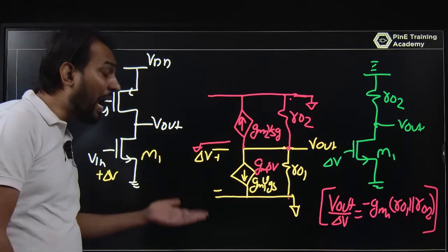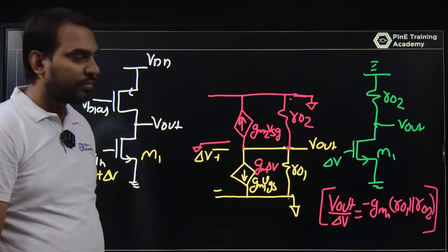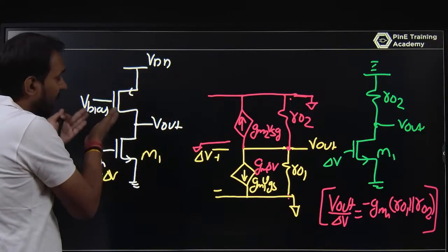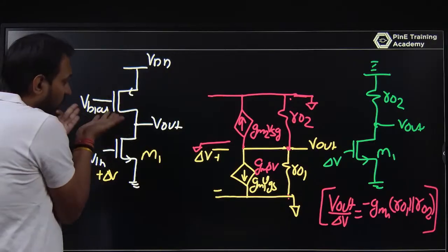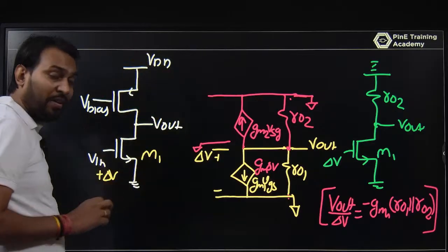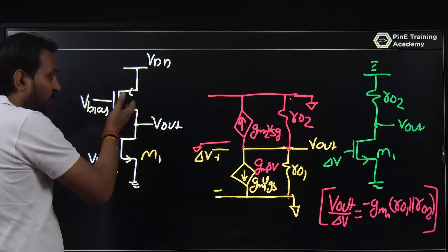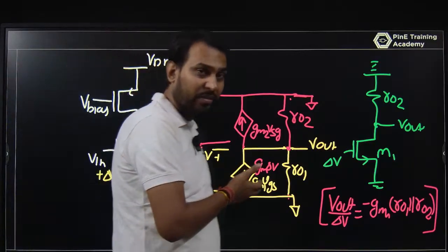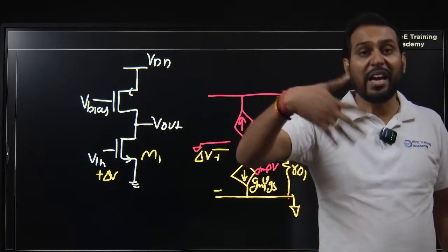But if you are using a high resistance, that will be a problem in terms of layout. So you can replace your resistance with a current source load with a PMOS or NMOS. If you are using this circuit, you are reducing the area. As a layout designer, as a circuit designer, you do not have a resistance. Of course, if you don't have a resistance, there is no heat. Resistance always absorbs the energy in the form of heat. It dissipates the energy.